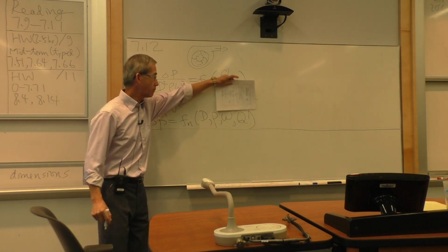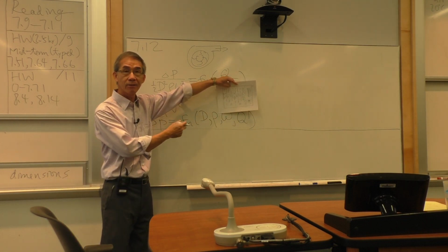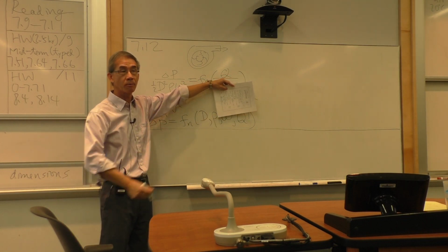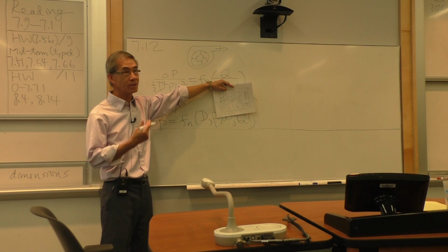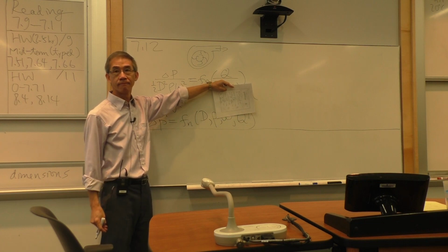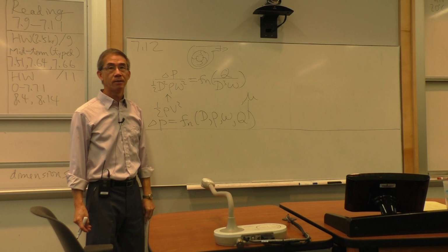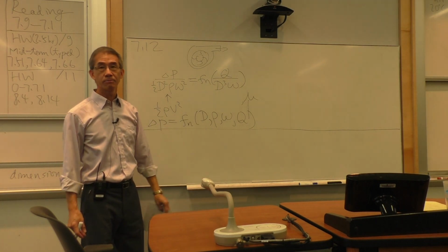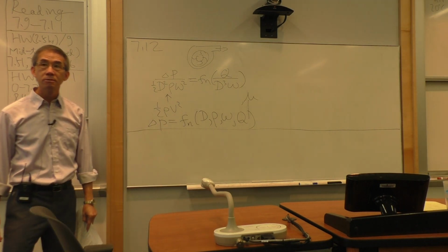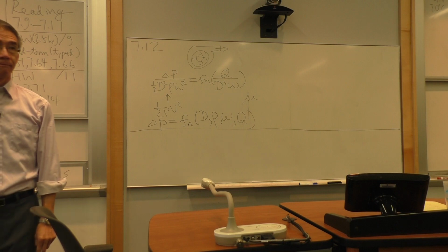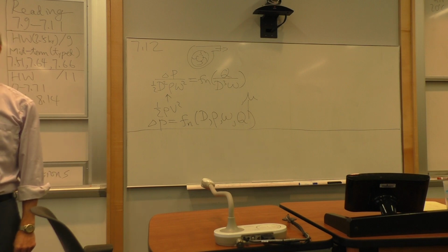We talked about last time, by neglecting viscosity, we are assuming the problem to be inviscid. The reason I did it is because it's simpler. Now I throw in viscosity. Can you immediately tell me by inspection how the answer will change? How many pi terms, instead of 2? 3. What's the third one?